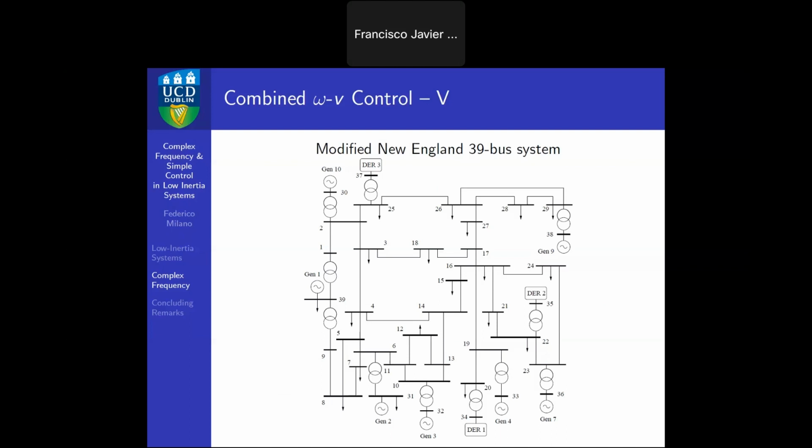Yeah. No, but there are still controllers that regulate V. The controller regulates V. It's not regulating rho. It's regulating V. So we are doing what we are expected to do. We want the voltage to be closest to the reference voltage and the omega to be closest to the synchronous frequency. What we estimate for a quality evaluation is this index, instead of looking only at omega or only at V during the transient.